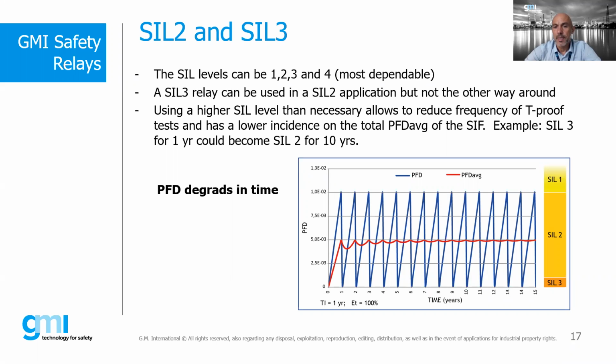Coming back to the initial question, can I use a SIL3 relay in a SIL2 application? Yes, because I can have a SIL3 relay that is valid for 1 year, but could remain SIL2 for 10 years. So I can use the same relays, and in our manuals we write clearly that the SIL2 level is valid for a number of years that is higher than the number for a SIL3 application. Hope we answered this question.